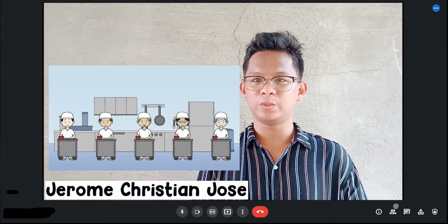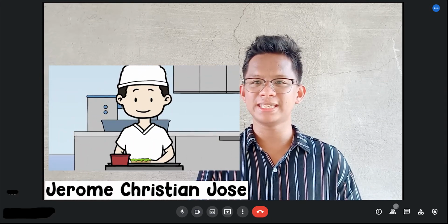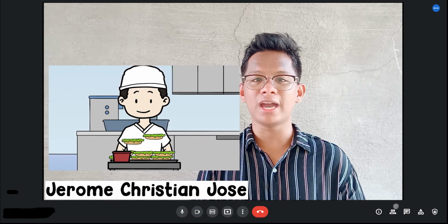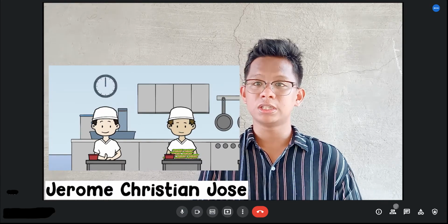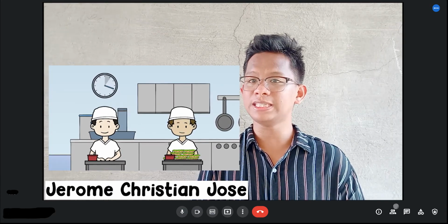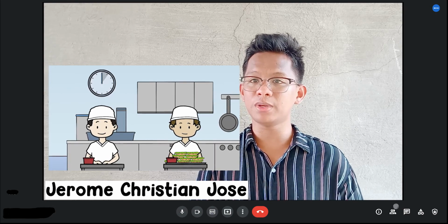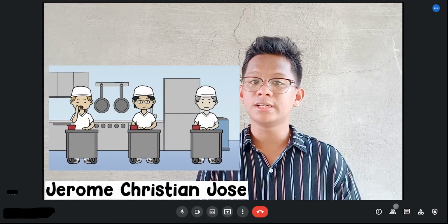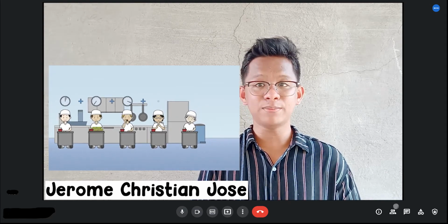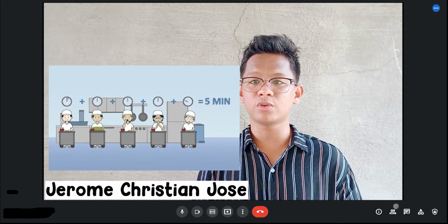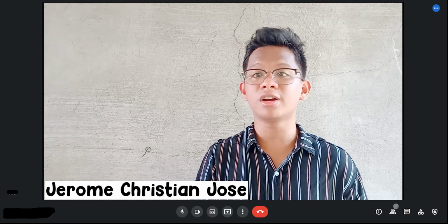The opposite of one-piece flow is large lot production. Although many companies produce in large lots or batches, it builds delay in the process. No items can move on to the next process until all items in the lot have been processed. The larger the lot, the longer the items sit and wait between processes. Larger lot production can lower a company's profitability in several ways. The lead time between customer order and delivery of product is lengthened. Labor, energy, and space are required to store and transport the lot. The chances for product damage and deterioration are increased.